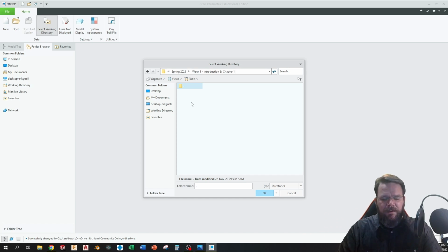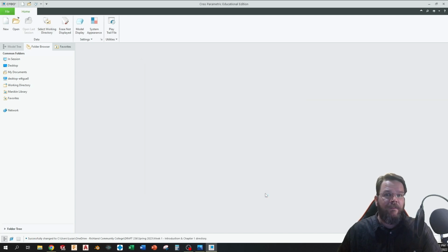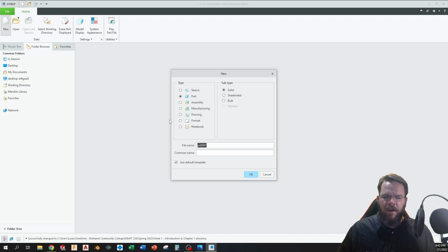So select your working directory, decide where you're going to save all of your files, and keep them organized from the beginning. So this is where I'm going to keep mine, Introduction in Chapter 1. Save yours wherever you want. Once your working directory is selected, we are now ready to go. We're going to click on New, and it's going to bring up our new file dialog box. We're creating a part, so we're going to leave this on part. It is going to be a solid, so we're going to leave it on solid. And we just need a file name.